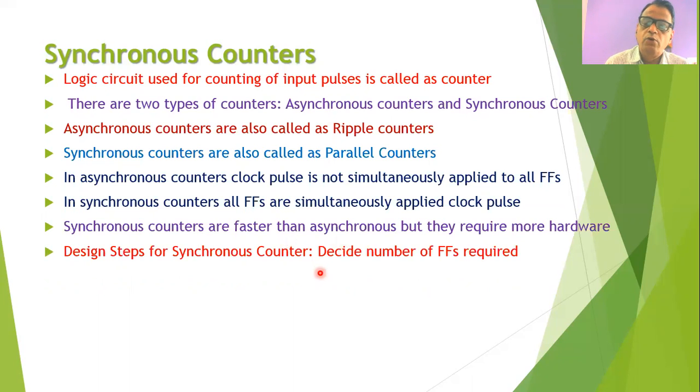Now, whenever we want to design any synchronous counter, there are certain steps that need to be followed. In the first step, we will decide how many flip-flops are required. Because if there are only 2 pulses to be counted, then we will require 1 flip-flop. But if there are 4 pulses to be counted, then we will require 2 flip-flops. So in the first step, we need to decide how many flip-flops are required for the counter.